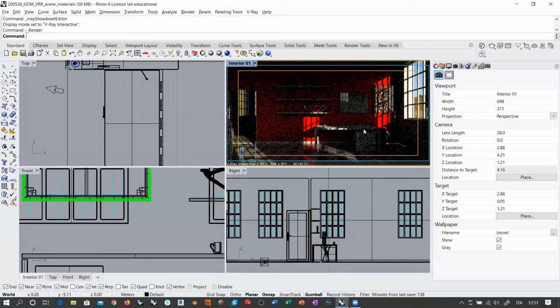It has a tone. So it's like if you take red, for example, and you convert it in grayscale, red becomes something like a mid to dark gray. Okay, so that's the light intensity that is actually being diffused by the primary rays of global illumination calculation. Okay, so this is why the scene becomes darker.